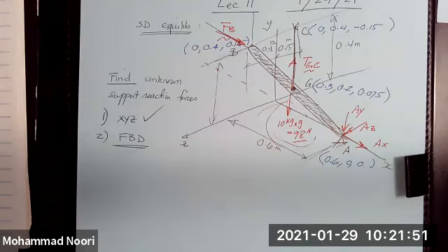In what direction can you not move it? You cannot push it against the wall. It doesn't go through the wall. So the wall is exerting a force on that ladder at that point, and remember that a force of reaction support is always perpendicular to the direction of motion.